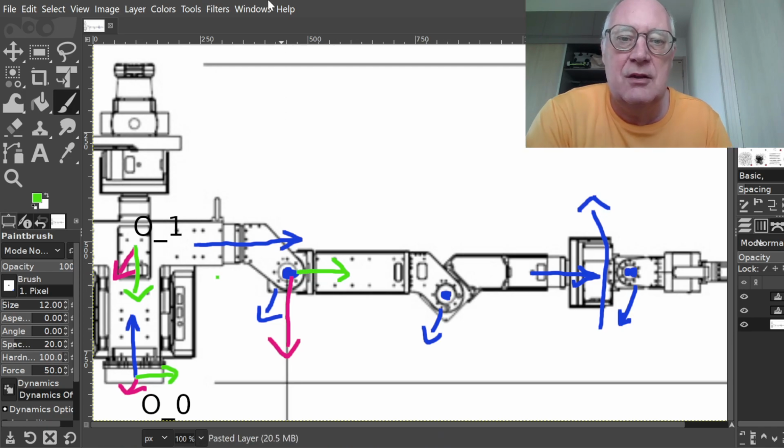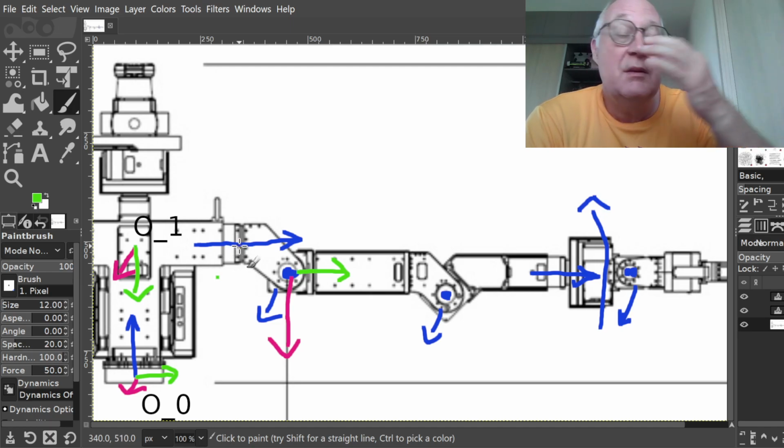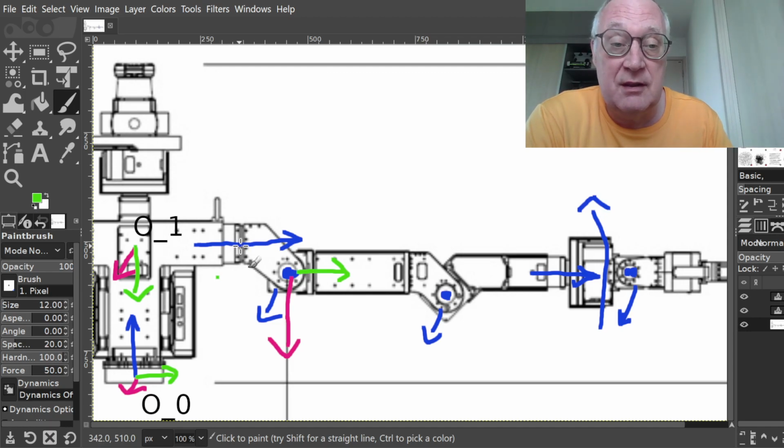So one thing that I don't particularly like about the Denavit-Hartenberg convention is, for example, that the origin of this coordinate system here is actually quite far away from where the servo horn is, right? So I'd rather do a couple of more transformations to bring it there, and then when I print out the coordinates of this, the translation vector, then I can sort of guess where that motor is located in 3D space at this point in time. When I'm just doing debug outputs, it's much easier to visualize the thing.